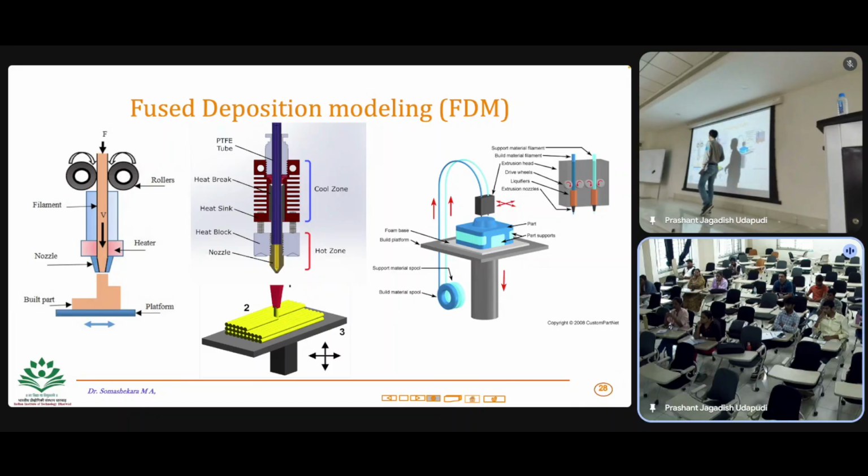If you see the 3D printer at your office or lab, most of the time clogging will happen, because you may not have enough heat transfer through the nozzle. Somewhere at the tip of the nozzle, the material will start to accumulate, and it is mostly exposed to the environment, which creates another problem. That's why you need to clear it regularly, so that you keep the nozzle area clean and can fuse properly.